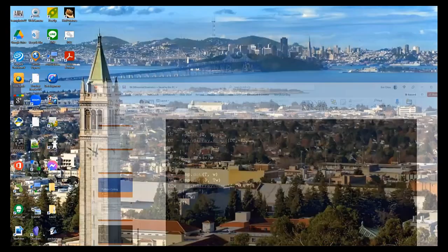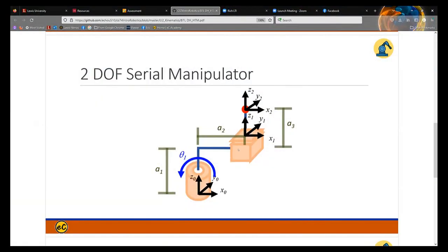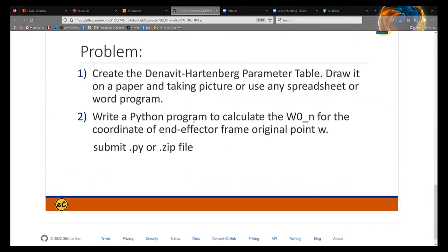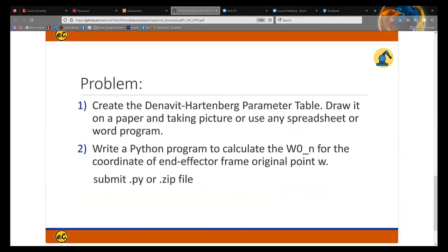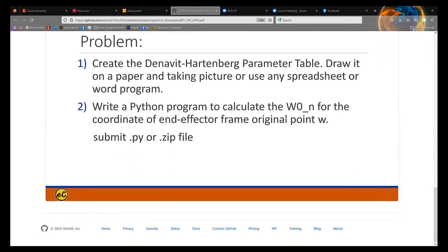Okay, that actually is similar to the tumble. It's just like you are rotating over here, and then the tumble goes up and down here, right? Is that okay so far? So this one totally you have 3 frames, 2 joints. 2 joints, 3 frames, and you need to create the Denavit-Hartenberg table, and then do modeling and do programming on it.